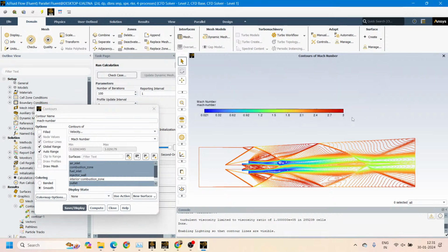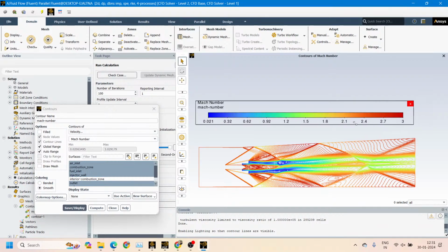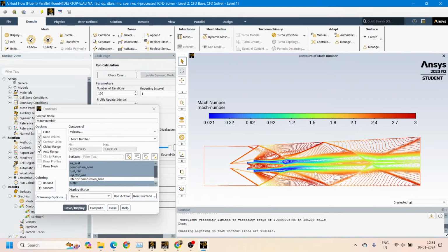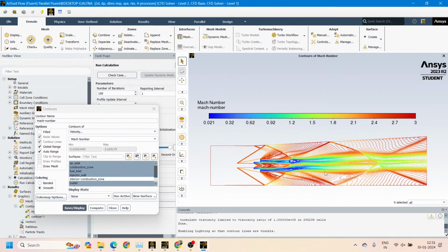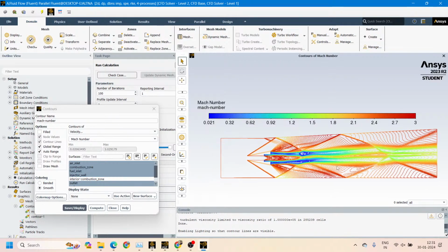And now if I want to save this, first I will adjust this scale equal to our contour. Keep some spacing between the scale and the contour, and keep a little zoom. To adjust, press Control, press the middle mouse button, and we can move it anywhere. How do we have to do it? Press Control, press the middle mouse button, and we can move it anywhere.